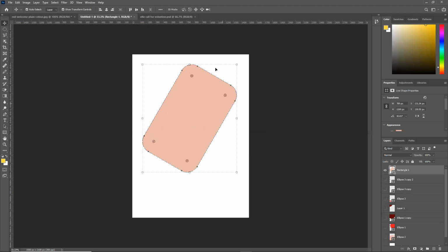And here you can see that all the sizes are moving. To prevent this, I can come to this point and untick the link. Because they are linked, all the editings will be applied to all of them. But I want only maybe one side or two sides.